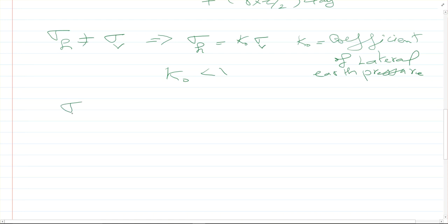Now we can visualize that the vertical stress in dry soils, I cannot emphasize this enough, is the stress in the soil itself. Nothing else is sharing the stress with it. It's just the soil loading itself and carrying the stress. Okay, now that is the case of dry soil. Let's now talk about wet soils with water.